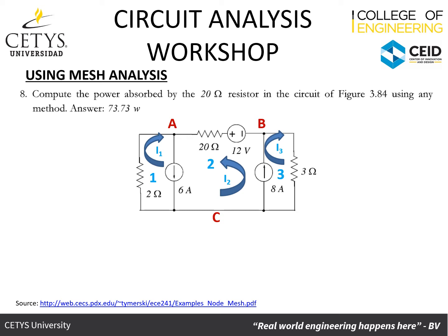So now that we've established the mathematical expressions that represents what's happening in the circuit, what we're going to be doing now is trying to reorganize these so we can work with them. And so for mesh 1, what we're going to do is represent that expression with regards to VAC and current 1. So VAC is going to be equal to minus 2I1, and we're going to call that equation 1. For mesh 3, we're going to grab that equation and we're going to represent that with regards to VBC and I3. So VBC is going to be minus 3I3, and we're going to call that equation 2.